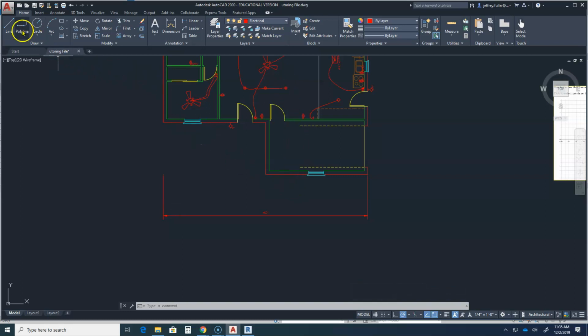Okay, so the next line is my major walls. So major walls again, I'm going to go to the end and start there. I'm going to go to this first break in the wall, and then I'm going to do the same thing again. I'm going to hold the shift button and type the @ symbol, and then this one is going to be 0 in the x-axis, tab over to the y, and it's going to be -6 feet.